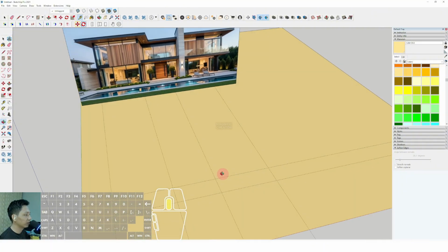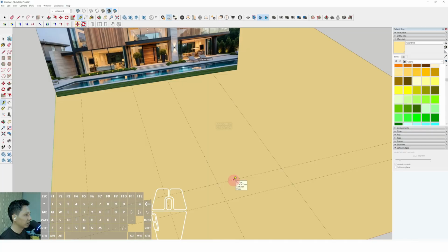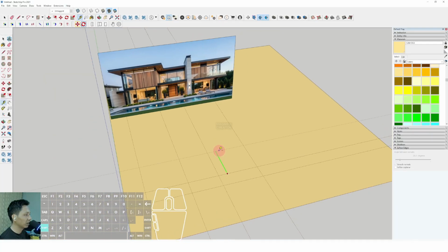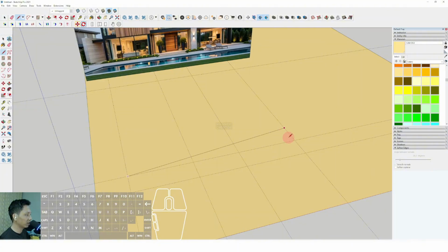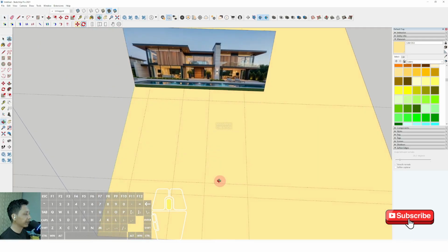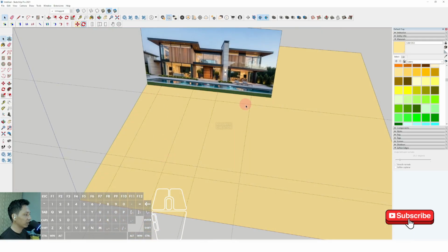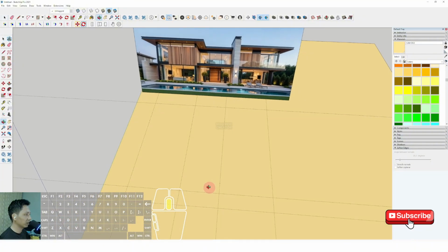And we can click from this position to the behind around 16 meter, and enter. Now we can measure from this point until this point, which is around 6.5 meter. So this is a square floor plan, approximately like that.